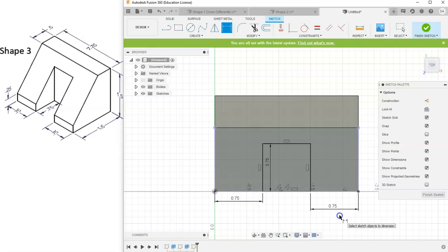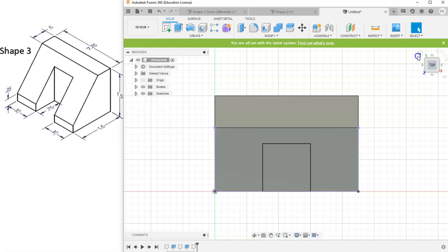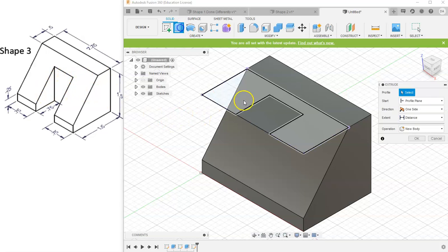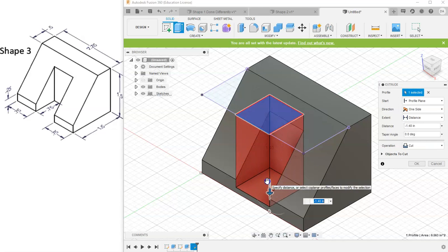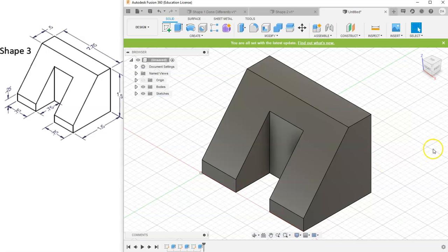And hit enter. And at this point, you might not see how this is a rectangular cutout. You might just be trusting me and just following along. So let's go ahead and finish our sketch and see if I can hopefully help you understand how this is clearly a rectangular cutout that is just slanted inward. Let me go to extrude, and I want this rectangle to cut downward into our shape. And hopefully it makes it just incredibly obvious how this rectangular cutout works. So I want to go from distance to all and hit OK. And there you have it.